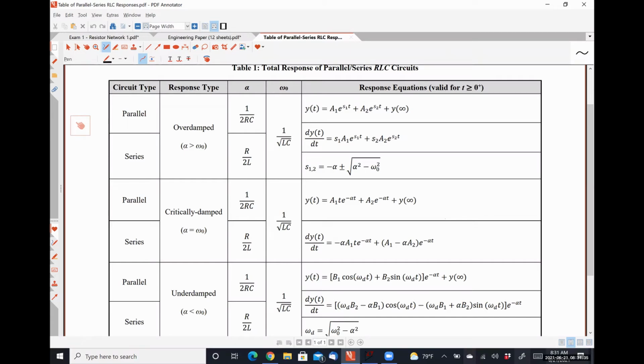And so I know that we explicitly derived everything here having to do with really the voltage drop across the capacitor. But Kirchhoff's voltage law and Kirchhoff's current law are going to force all voltages and all currents to be of that exact same mathematical type. So they're all going to look like a sum of exponentially decaying functions.